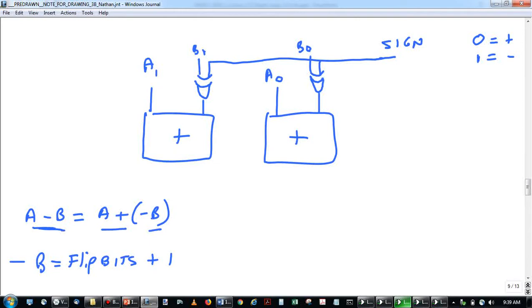Okay, that's a little bit more tricky, but let's have a look at this XOR gate. So how does an XOR gate work? What does it look like? How do you remember the XOR gate? Okay, so the comment was, if they're both the same, it's 0. If they're different, it's 1. Great, yep. You can also just remember the pattern. It's the only pattern that's different from the rest of them. But absolutely, if they're both the same, 0. If they're different, it's 1.